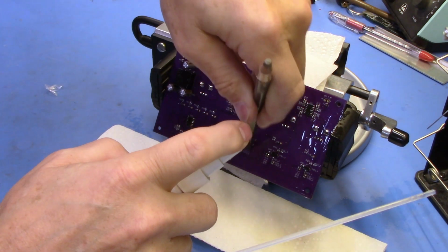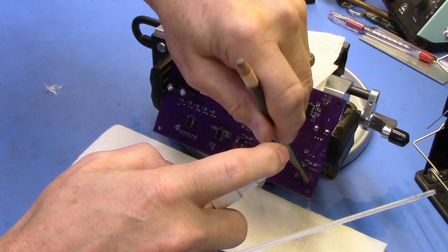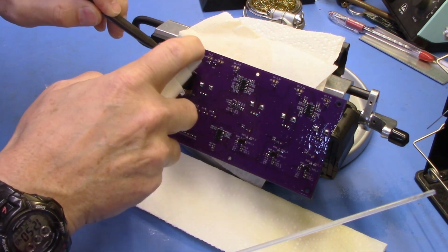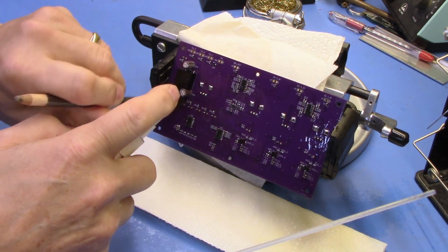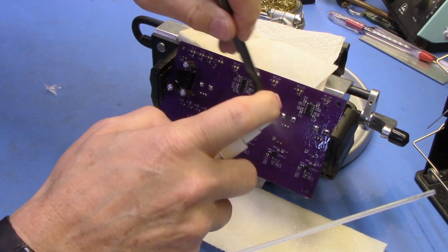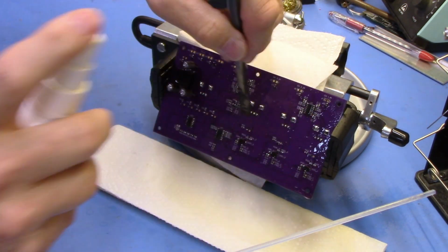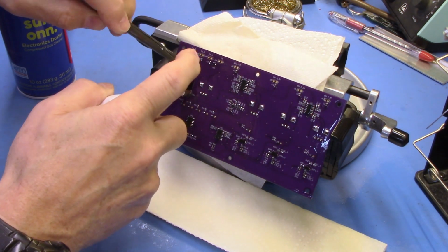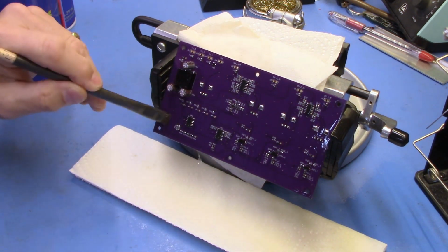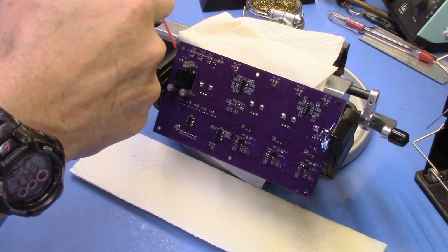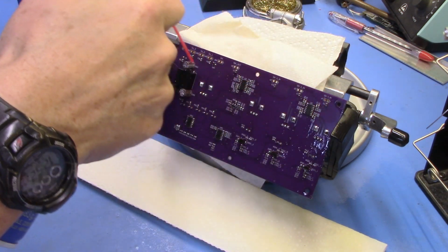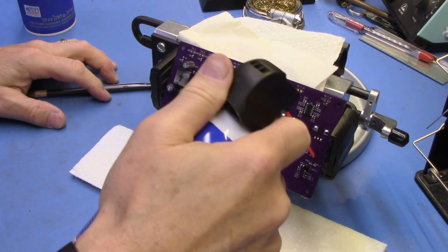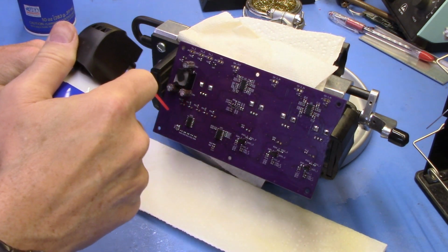Residue stuff on the board can be highly conductive and just make stuff not work. And I've had several instances where I had not cleaned a board sufficiently and the circuit just totally didn't work, or it worked weird. I closely inspected every solder joint and they were all good. There were no solder bridges, there were no other anomalies to explain the circuit's weird behavior. So I went back and re-cleaned the board and it magically just started working exactly as designed.